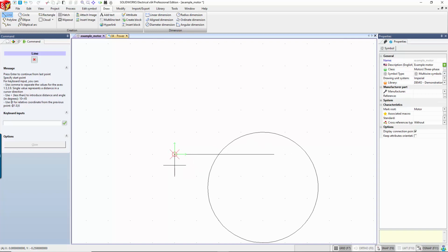When I think about how this symbol is going to exist on the drawing or how I'm going to use it, a lot of my drawings, which are on B-sized, sometimes D-sized sheets, I tend to want my wires to be spaced 1/4 inch apart. If I have the legs of my symbol set to 1/4 inch apart, then I'm going to be very easily able to draw 4 wires 1/4 inch apart up to my symbol. It takes no time at all.